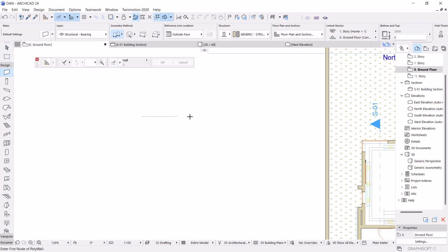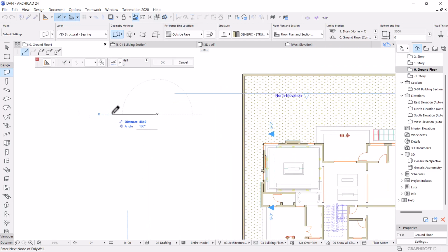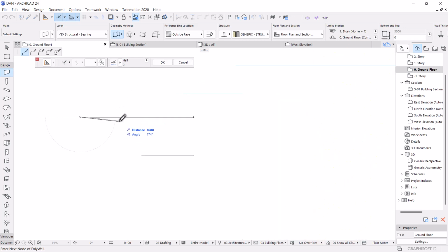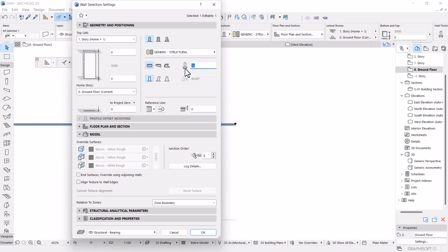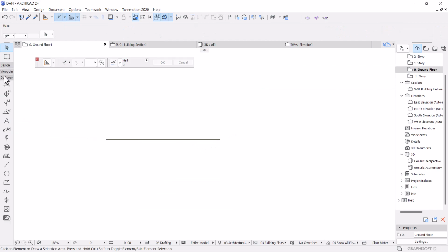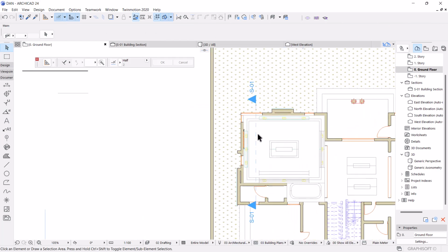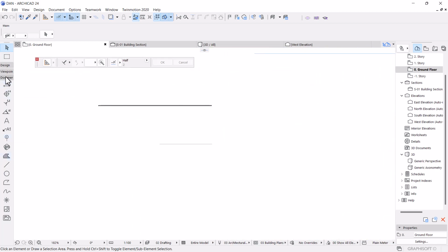So in this case let's continue with the wall tool. I'm coming to this point and drawing a wall. The wall is just any length, and I can click on it. I want it to be very thin, 15 mm is okay for me. Then you can either drag this section to this point, or have another section, so let me draw a new section here.